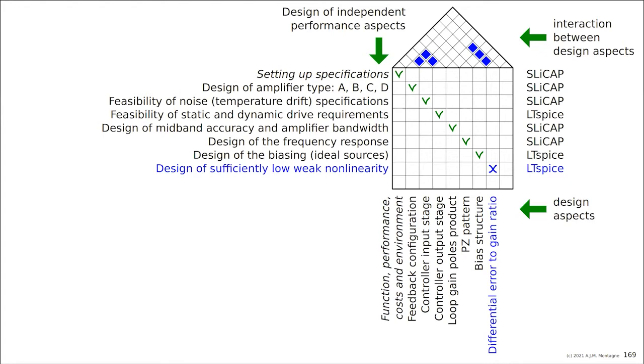Minimizing that can be done by adding a stage, but then the stage should not add a lot of nonlinearity, because then at the end it does nothing. So we are not going to add an output stage. We're putting some stage in the middle, of course. We have already the output stage. The output stage was a nuller-like stage, which means that the stage driving it doesn't need to have a large signal, so it doesn't have a very high nonlinearity.